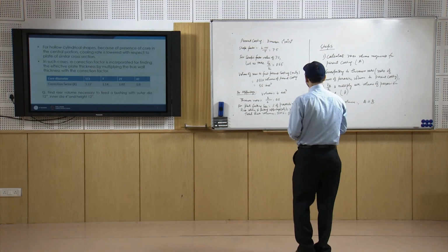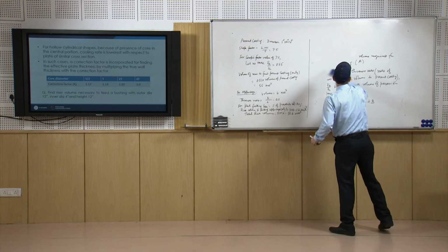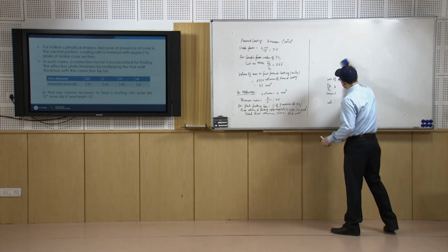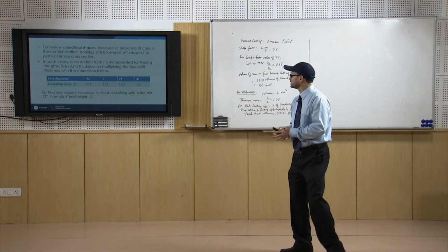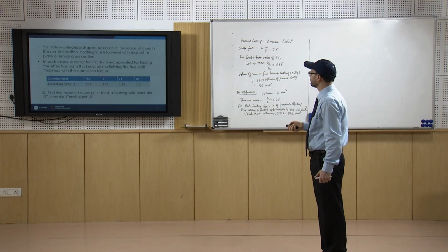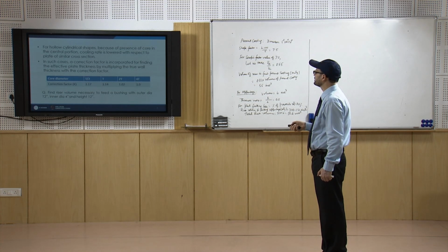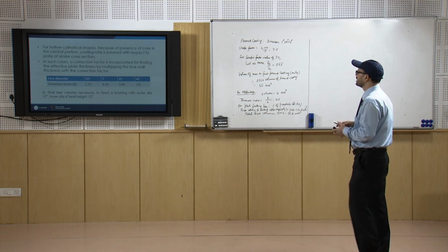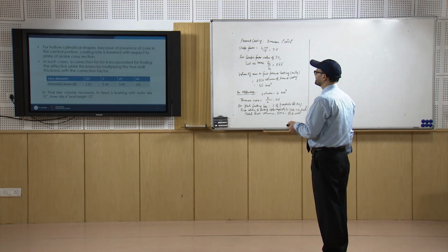Now, we can see how to calculate in such cases the volume of riser metal required. Suppose you have to find the riser volume required for a bush with outer diameter 12 inch, inner diameter 4 inch and height 12 inch. First of all, you have to find the correction factor.